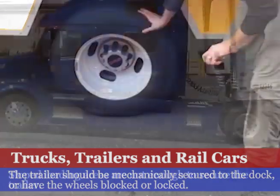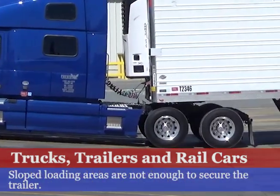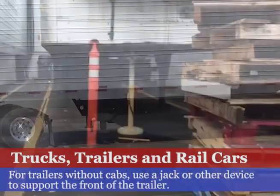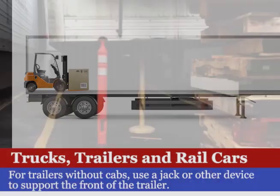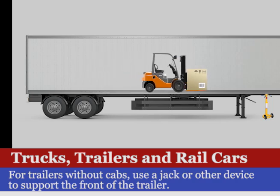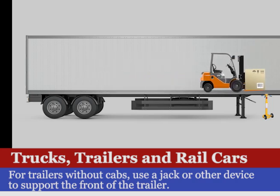A sloped loading area is not sufficient, by itself, for securing the vehicle. If there is no trailer cab, use a jack placed at the front of the trailer. This will prevent the trailer from collapsing, or flipping, when the forklift enters the front of the trailer.